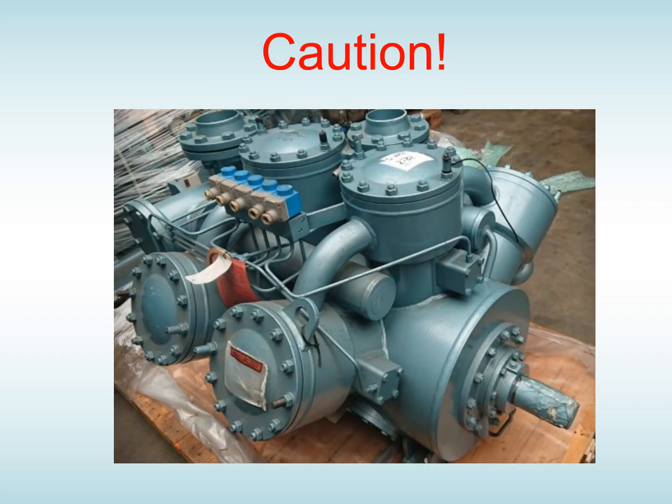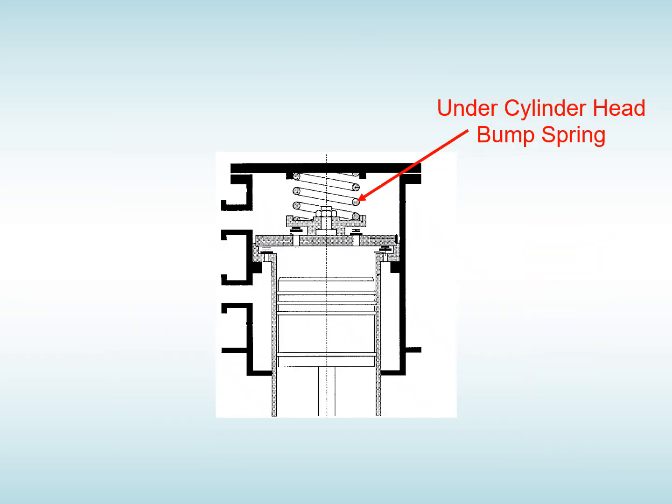Now, just a word of caution if you're working on reciprocating compressors. If you see large studs like that, beware. It generally means that there's a big spring underneath the head. So you remove all the other bolts and gradually release the spring tension using the longer bolts.